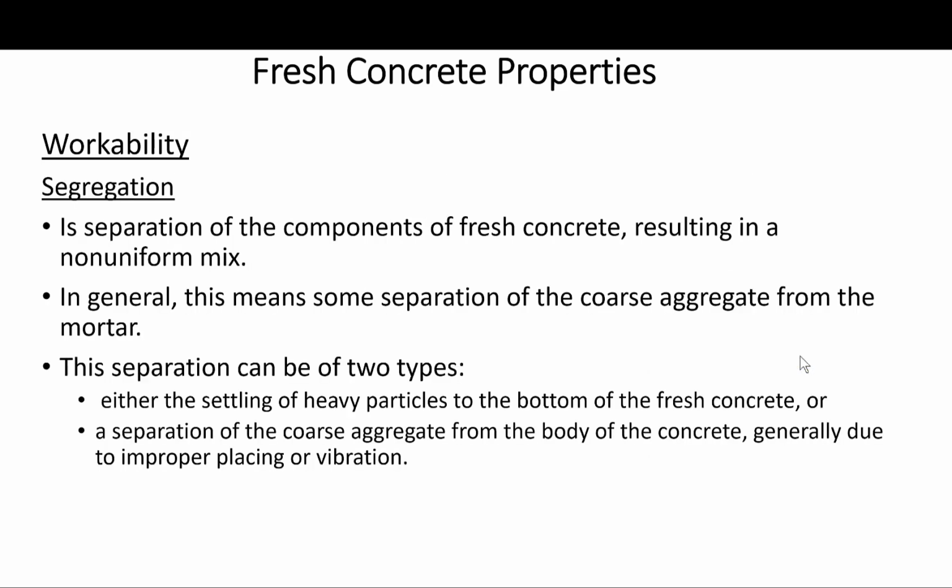So let's look at what segregation and bleeding are. Segregation refers to the separation of components of fresh concrete, resulting basically in a non-uniform mix. In general, this means some separation of the coarse aggregate from the mortar.